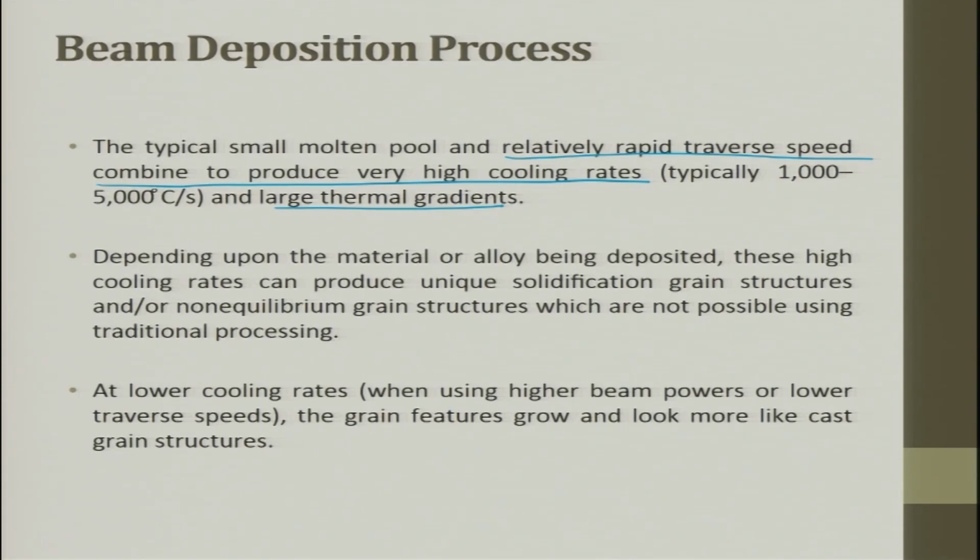You should try to avoid having large thermal gradients, because if you have large thermal gradients, it is going to warp the surface. Instead of a flat plate, you will get something like a warped plate. Okay. This is flat and this is warped. So, large thermal gradients should be avoided. For this, what we do is we try to do the entire exercise or the product development in an ambience where the temperature is maintained at a certain level, so that the thermal gradient is avoided.